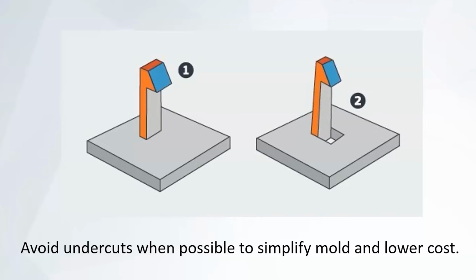Let's take a look at a snap. This type of snap is very common. And what you'll see is underneath the snap part that overhangs, this part here is an undercut area. You would have to have the plastic of the mold fill this in to keep this from filling with plastic.